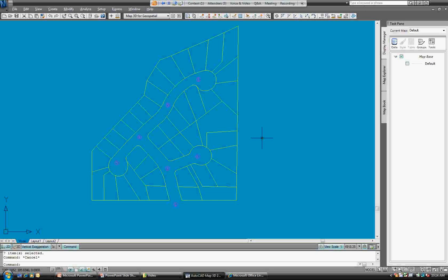So continuing on here, in this next hands-on, let's take a shapefile that's got contours in it, bring that shapefile into a drawing and take those contours and create a surface from it. Those of you that have done this process in the past know that it can be quite cumbersome, with several steps to get contours to actually have elevation on them.